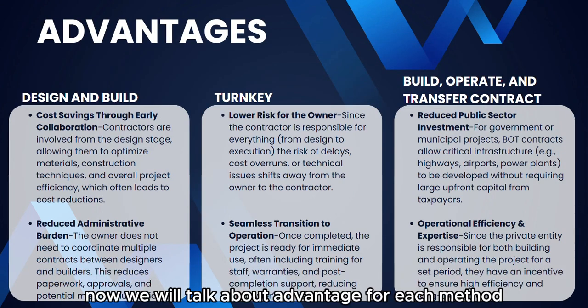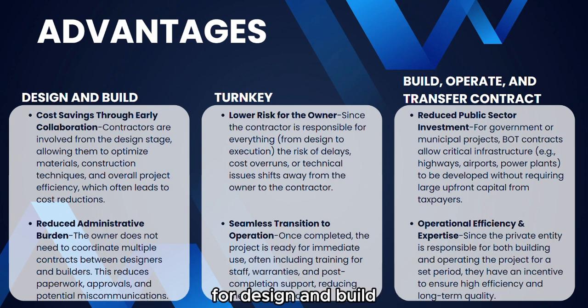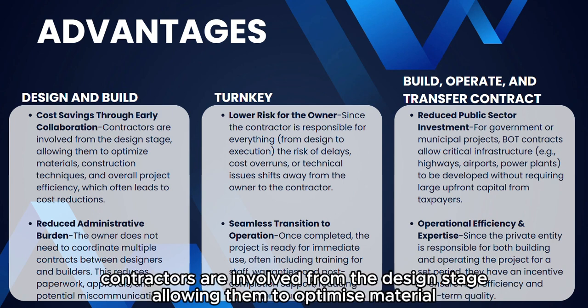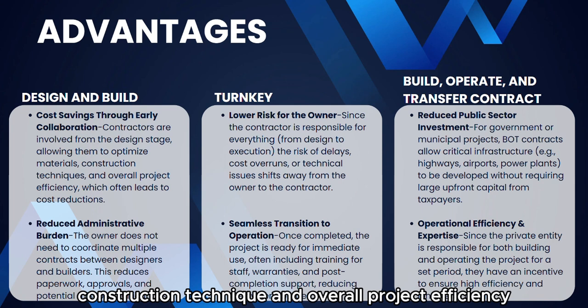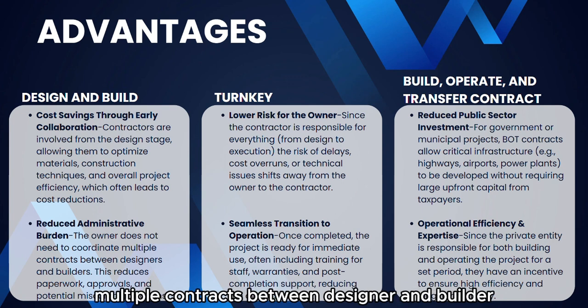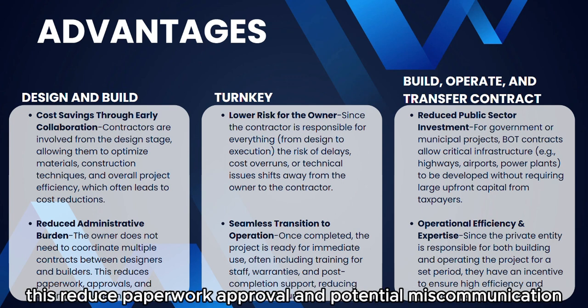Now we will talk about advantage for each method. For design and build, first is cost saving through early collaboration. Contractors are involved from the design stage, allowing them to optimize material, construction technique, and overall project efficiency, which often leads to the cost reduction. Second, reduce administrative burden. The owner does not need to coordinate multiple contracts between designer and builder. This reduces paperwork, approval, and potential miscommunication.